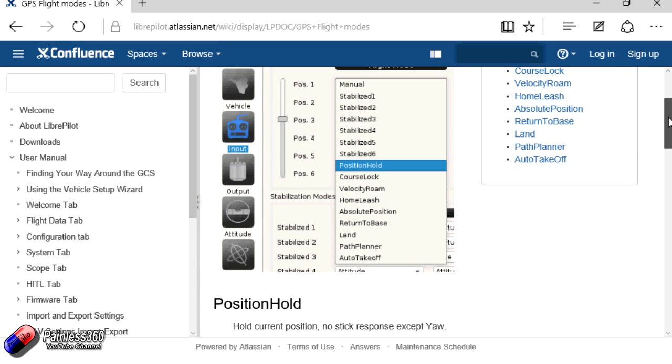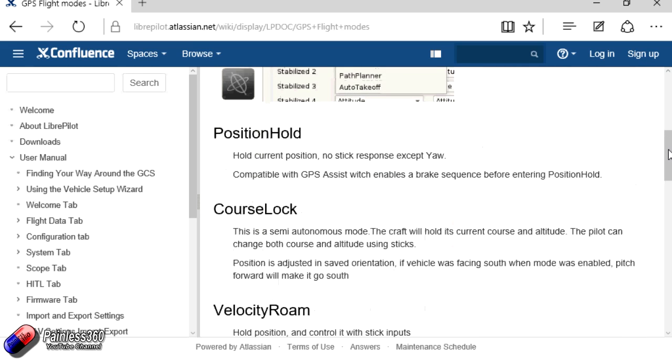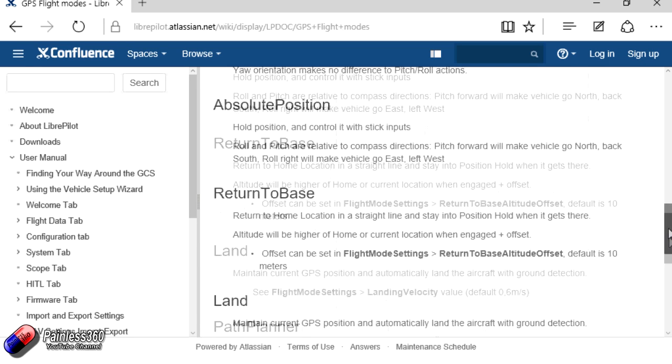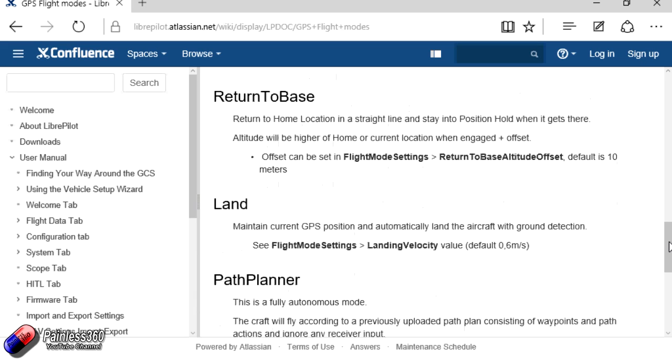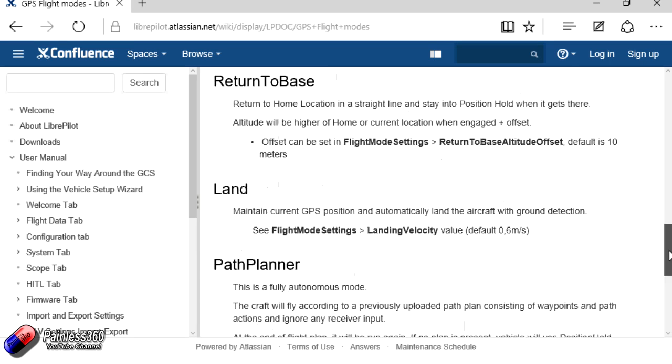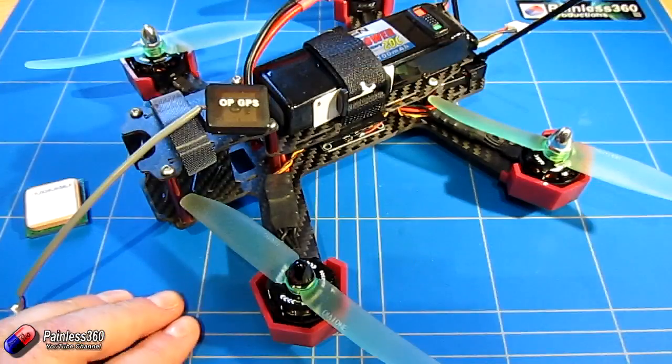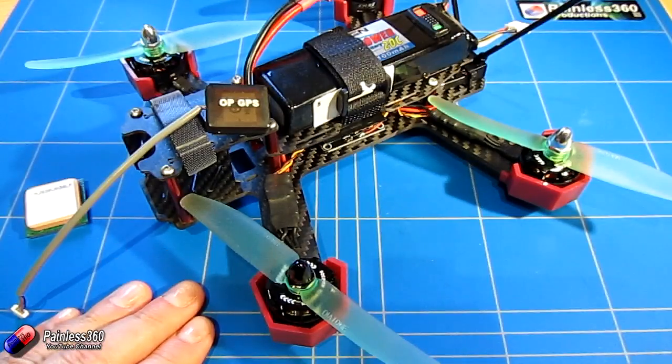The first is the ability to do a GPS home feature, where you can store the home location where you actually take off, and then if you get into trouble you can flick the switch and select that mode on your radio, or you can set up failsafe so it selects that mode and then the model will fly back to you. That's a really nice way to do it, and it means that if ever you get into trouble the model will come back home.